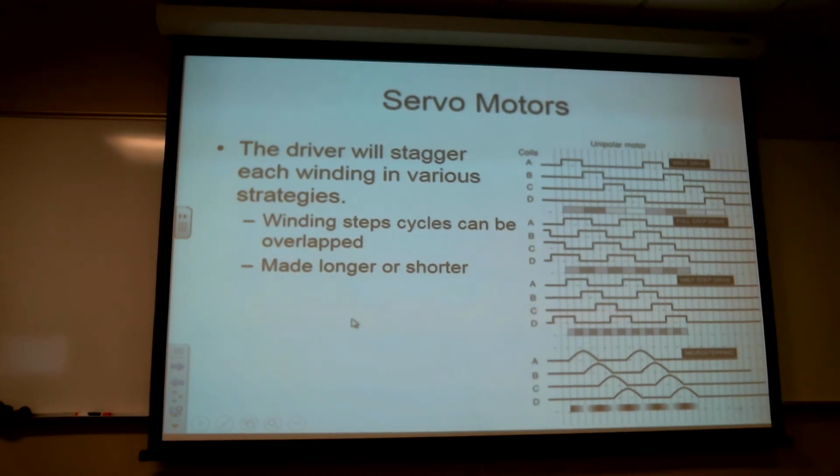If I put several gear assemblies in there, now each full revolution only represents 1,000th of an inch travel on the mill bed. Okay, man, I can get that. If I get 10 full stepper motor revolutions for 1,000th of an inch travel, I've got some pretty good precision there, right?